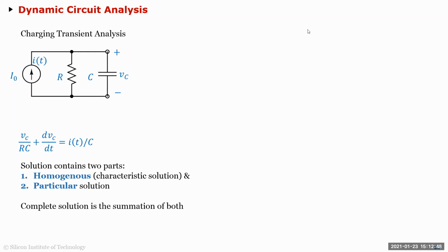A lot of times when you start modeling the SAR or the delta sigma, you'll see that for the op amp initially you might just use a VCVS. Then if you want to add more second order effects, like the input impedance not being infinite, you add a resistance equal to your input impedance. Let's say it's 100 kilo ohms, then apply 100 kilo ohms.